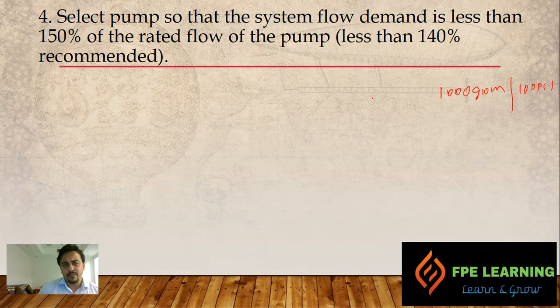So 1400 GPM is the ideal in this case, because maybe after 10 or 20 years of the life of the system, the flow and pressure go down and down and down. So giving a 10% allowance for those kinds of things is good for your fire pump system. That's the recommendation.